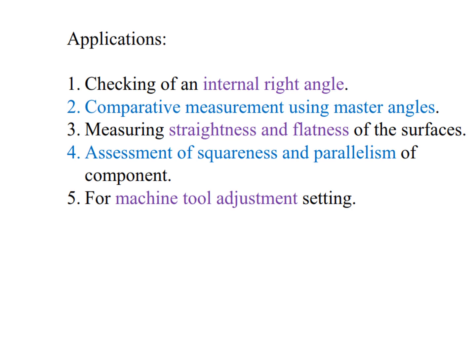It is used to measure roll angle and also pitch and yaw of slides, to assess the squareness and parallelism of components, for testing the accuracy of rotary tables and index tables, and for monitoring angular movements over prolonged periods of time, for machine tool adjustment, etc. So this is one of the best tools used for these applications. It is a non-contact optical angular measuring tool.